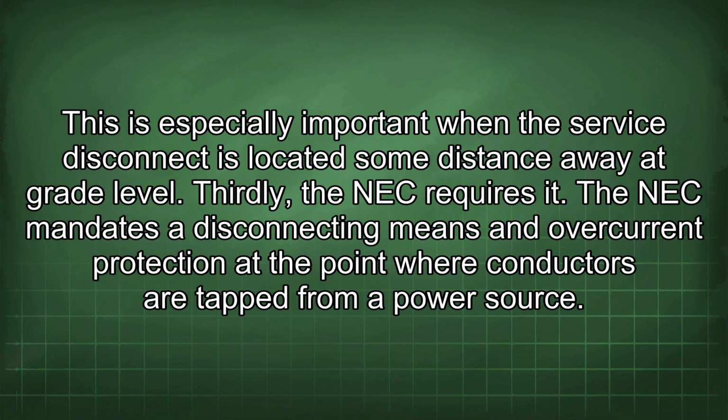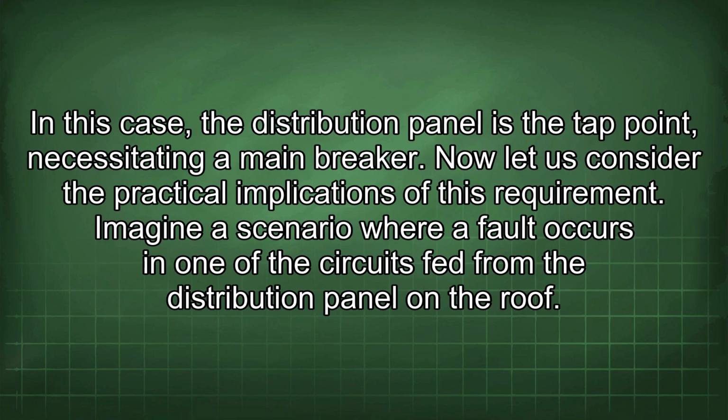Thirdly, the NEC requires it. The NEC mandates a disconnecting means and overcurrent protection at the point where conductors are tapped from a power source. In this case, the distribution panel is the tap point, necessitating a main breaker. Now let us consider the practical implications of this requirement.